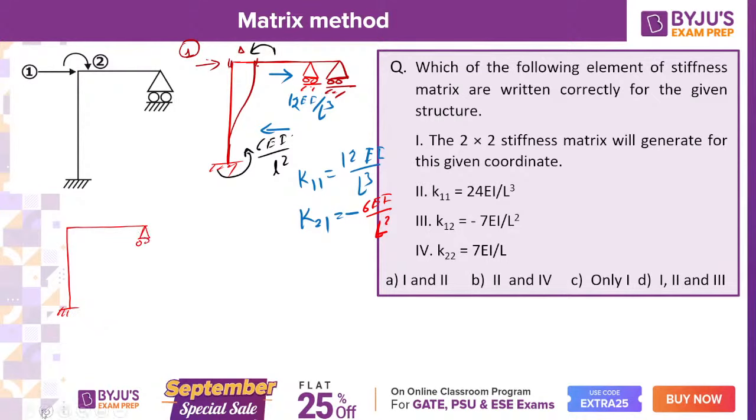Now the displacement will be seized or restrained here. By restraining the displacement, we provide the rotation at this point. Suppose we are providing the rotation in the coordinate direction 2. So to produce unit rotation here, this is the deflected shape of the beam. Far end is hinged, so here you need to apply 3 EI by L, and here you need to apply 4 EI by L.